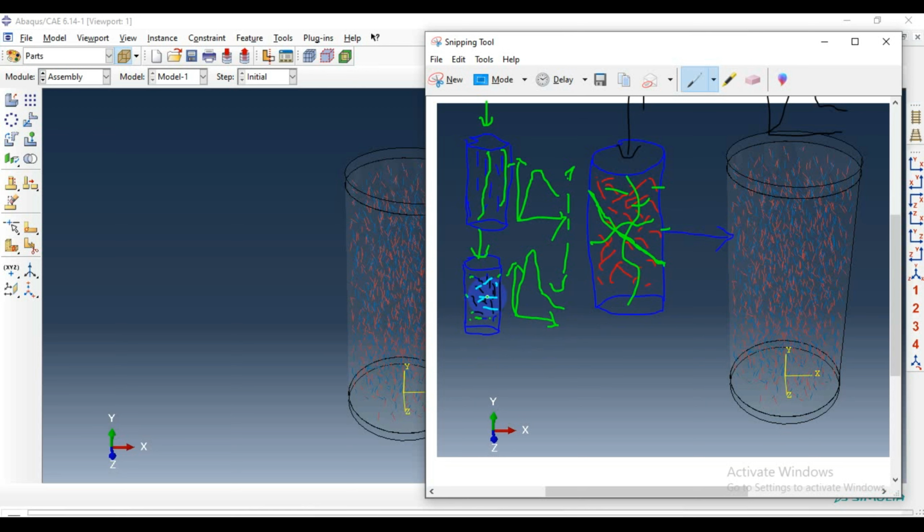And if randomly oriented discontinuous fibers are incorporated, they can also enhance toughness by preventing catastrophic failure, as they provide reinforcement in multiple directions, though less efficient than continuous aligned fibers in terms of flexural loading.